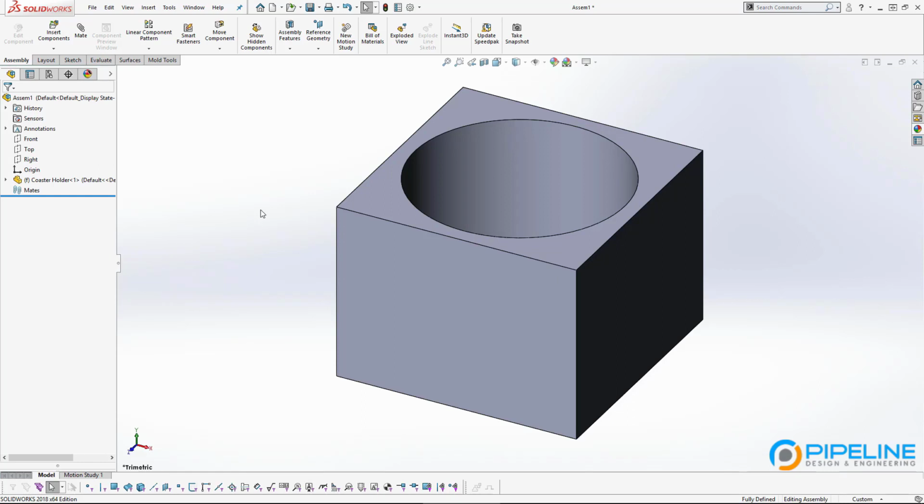Yeah, that's probably better. I was calling it sort of the anchor of the assembly, but foundational sounds better probably. Quite often it's like that bottom part that everything is stacked on top of. A lot of the assemblies we do are test fixtures that have a base plate, and they're 10 or 15 parts that are assembled on top of this base plate, so we'll use our base plate as that foundational part and make sure that's centered on the origin in our assembly, and then everything else assembles onto the base plate, for an example.